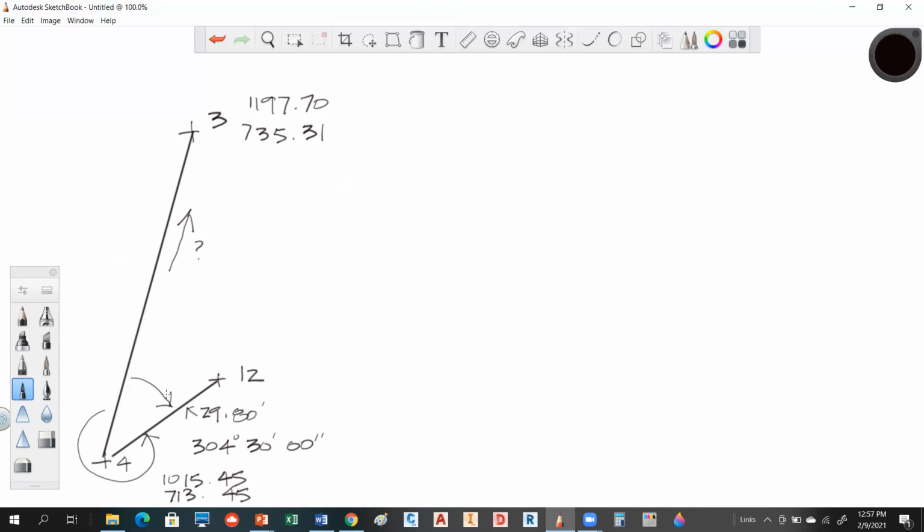So let's take the 304°30' and subtract that from 360. I get this guy at 55 degrees, 30 minutes and 0 seconds. So hopefully you can see that was just an easier process to even deal with. I wouldn't even mess with that. I just get rid of this. Okay, does that make sense?